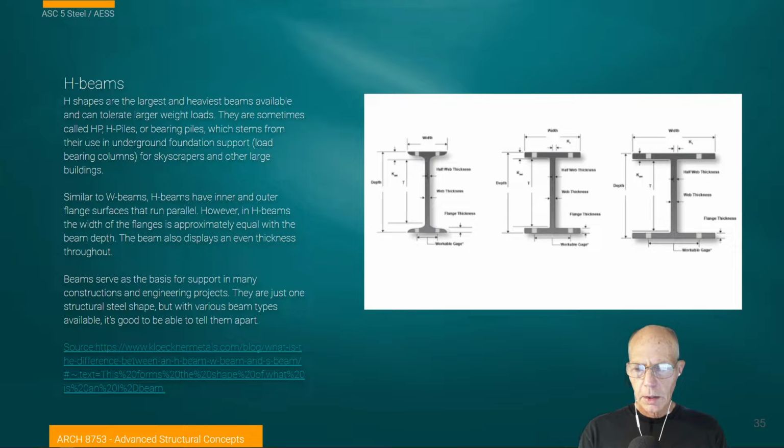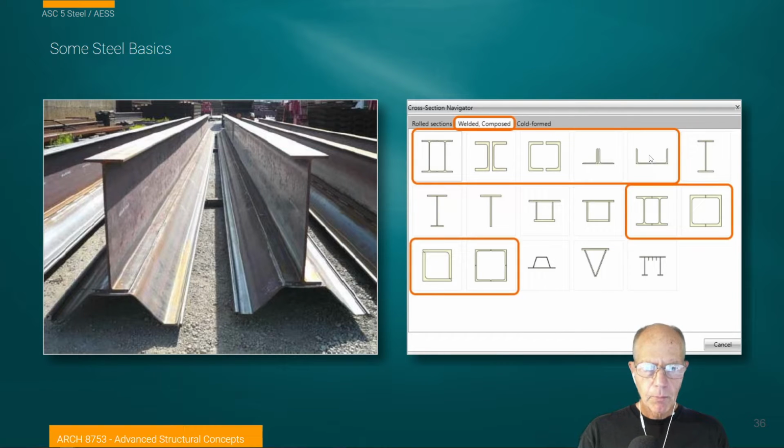Its geometry is more close to the idea that the section properties in the X and Y direction are kind of uniform. It's more like a column, so that it wants to bend in equal ways in both the X and the Y axis. And so we take a W flange, we stretch those top and bottom flanges out in order that it can perform better as a column.